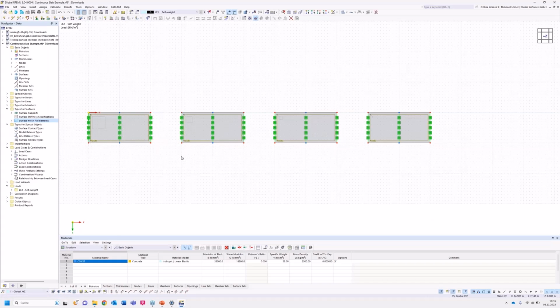And yeah, now we can also see these squares in our surfaces, and those show us how the mesh size will be. Like this will be very coarse and this will be extremely fine. You could estimate like this will be roundabout 1,000 more elements than the first one. Not 1,000 times more calculation time, but let's say 5 times the calculation time. It's just an estimation.